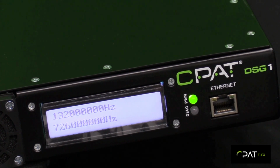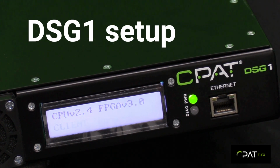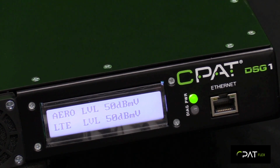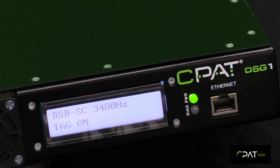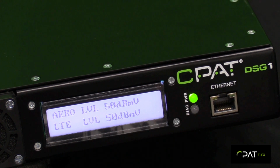Today we are going to review the proper way to set up the DSG1 in an all-digital CATV plant. The objective of this exercise is to determine the optimum CW QAM level offset, or delta, between the adjacent QAM channel digital power level and the maximum peak level of the injected DSG1 carriers. The delta value is required in order to configure the DRV3 detection device with the proper detection level parameters.